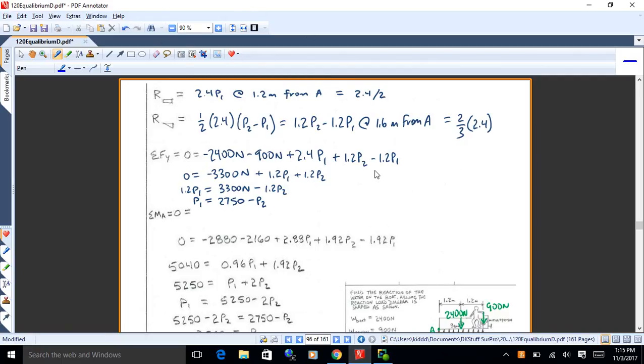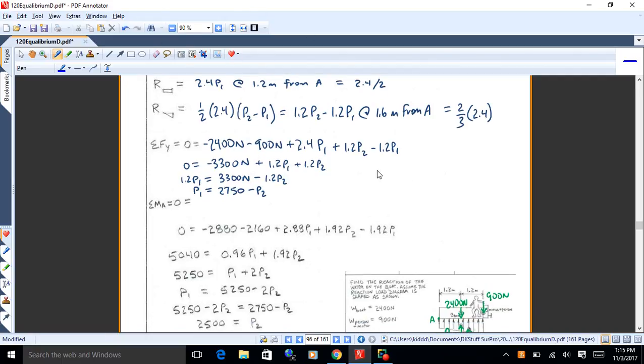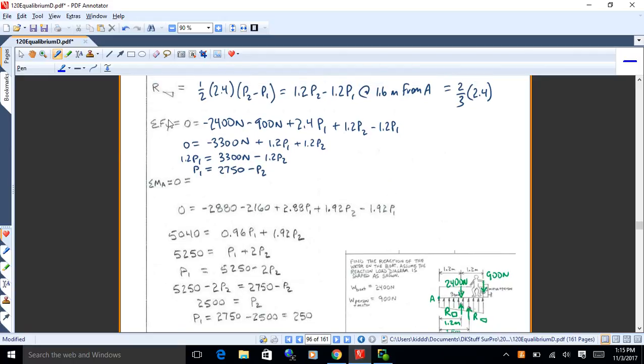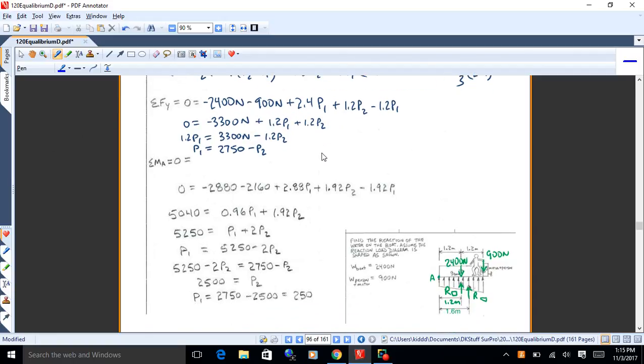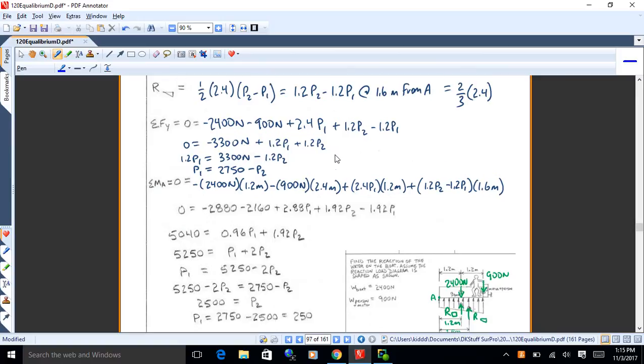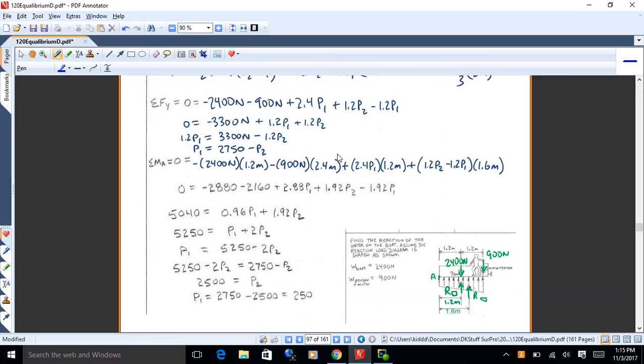And then we want a moment equation. You know, it's got 4 terms in it, so I'll probably look at that diagram. I've got all the dimensions on it that I need, and I've got the forces, so, you know, easy enough. I'll just use the force equation there, and I'll just add moment arms to all those terms. Watch out with the signs, though, because the force signs don't relate directly to the moment signs, so put your own signs in there. Okay, counterclockwise plus and clockwise minus.